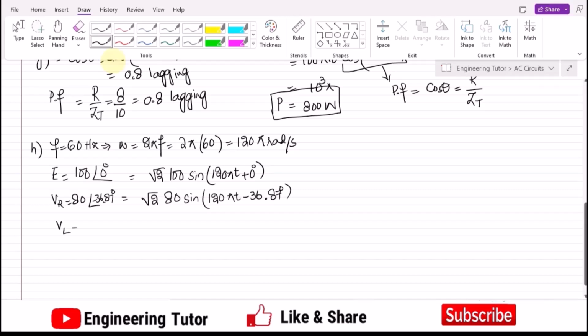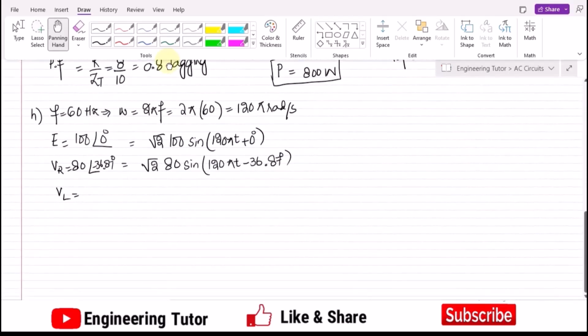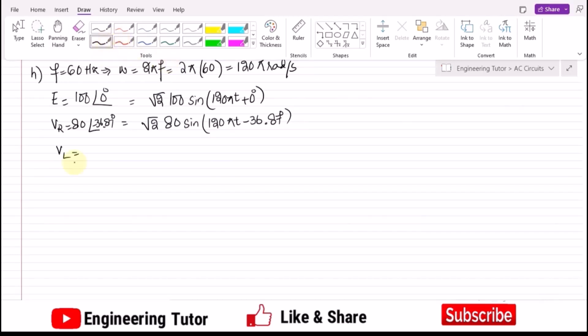Similarly, V of L, the value of V of L was how much? Let me see here, that was 60 volts, and the angle with it was 53.13 degrees. So the same procedure here, square root of 2 times 60 and sine of 120 pi t, and the angle is 53.13 degrees. Okay, so this is about all the voltages.